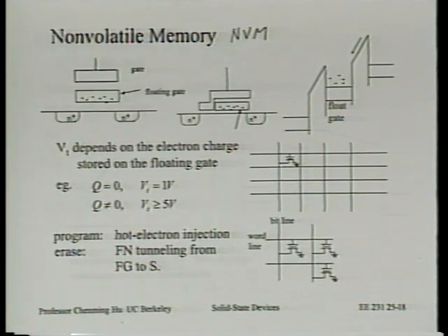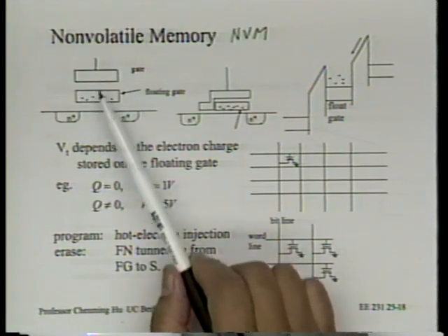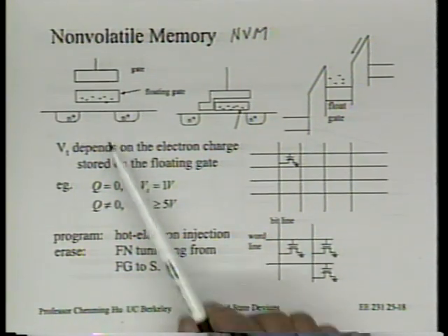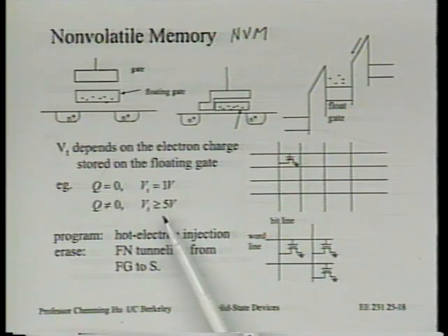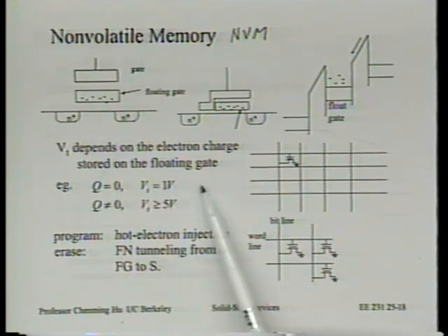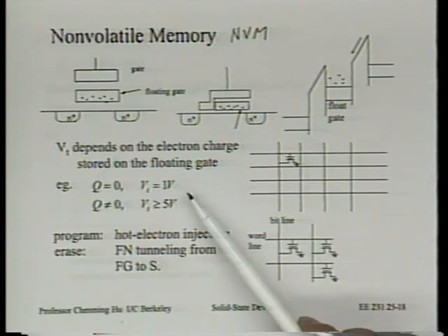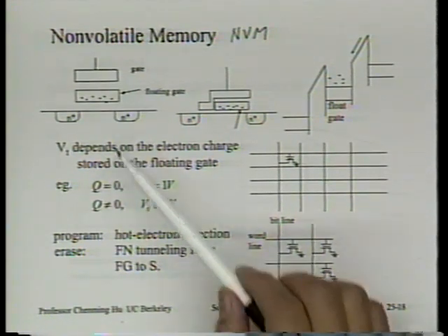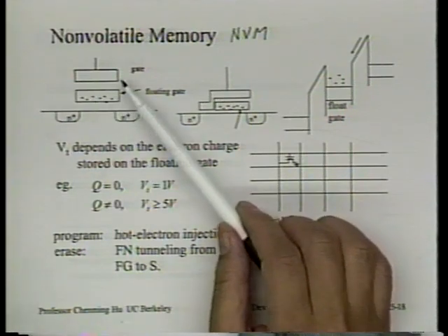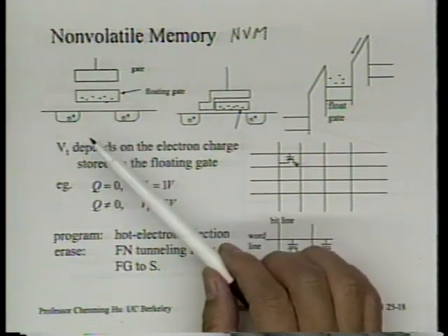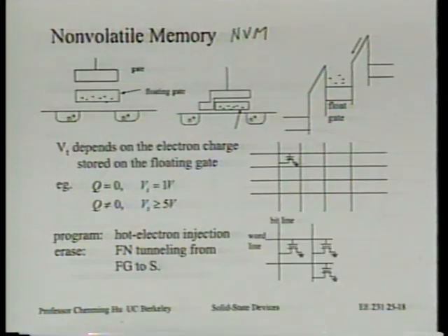They would do that by measuring the VT of this transistor, not just whether it's high or low, but dividing this into maybe, let's say, 8 steps. That's what's needed to store 2 bits of information, by the way. If you can store, I was wrong, I'm sorry, you don't need that. You need only 4 states. If you can store 4 states, and if your sense amplifier is sensitive enough to separate the VT, not just differentiate between high and low, but which of the 4 states it is in, you can actually store 2 bits of information.